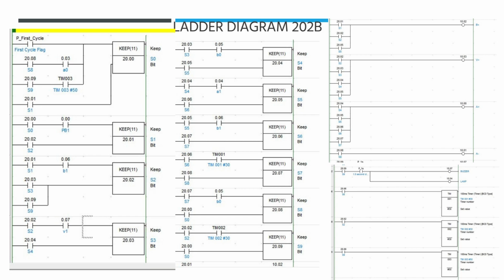If the object is not detected, after pressing the push button, cylinder B will extend. Then sensor V will trigger. Then it detects that there is no object. The alarm will blink for 5 seconds to show that no object has been detected. After that, the program will restart.